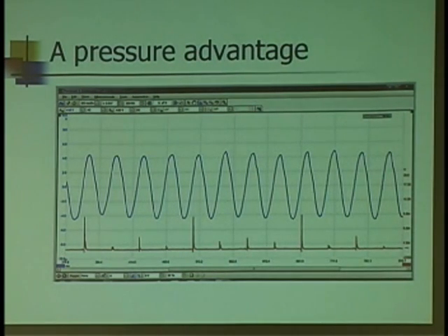Neat thing about the first look sensor, if I do find a low peak, identified a weak cylinder, it's got to be one of two places, right? Top end or bottom end. What if I move that first look sensor to the oil fill tube? What would I be measuring there? Crankcase pressure. What affects crankcase pressure? Isn't that the pistons moving up and down? Do the valves impact that? No. So what you're seeing here, that's the pulses in the bottom end as the pistons are moving up and down.